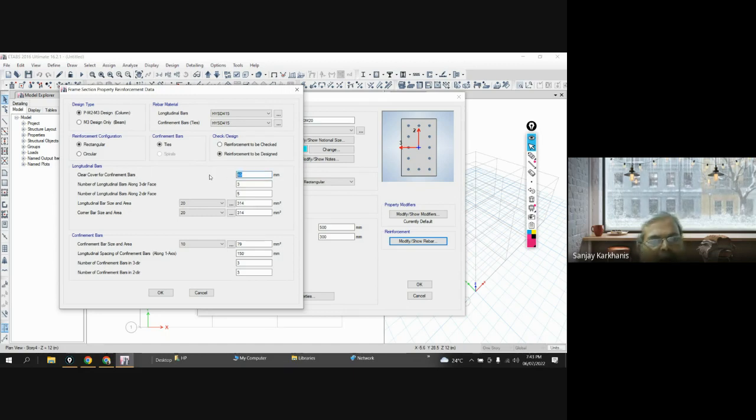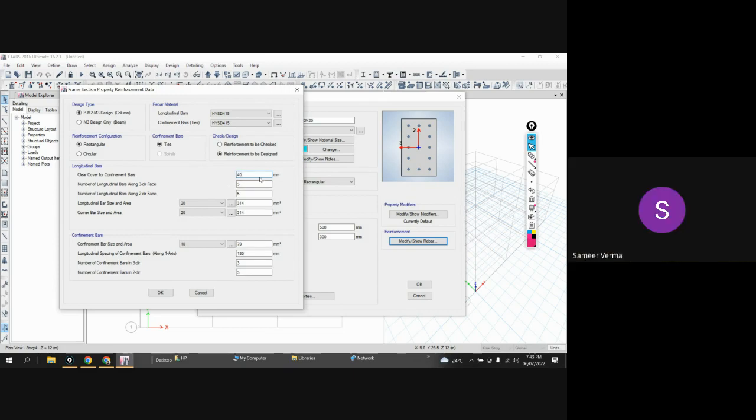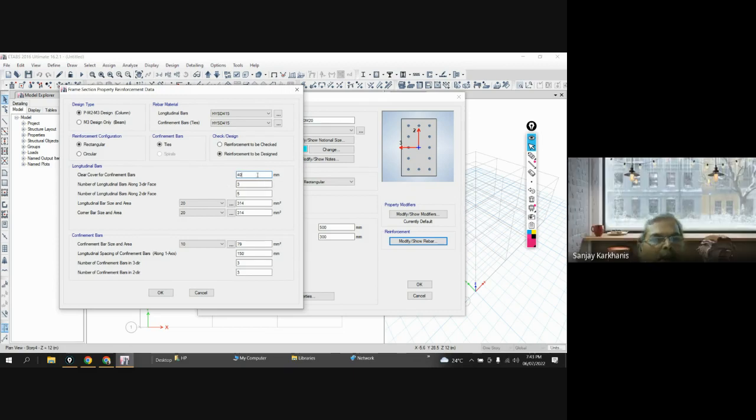So what is the clear cover? That is as per your choice. And if we follow codal provision, then for column we are providing a clear cover of 40. But if you want 50, you can do it. Again, never ever follow everything blindly. I will say that the code says the clear cover requirement for columns, beams, and slabs is not arbitrarily defined.